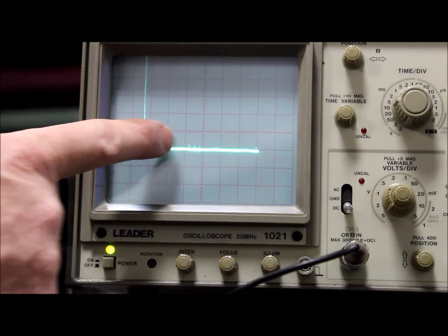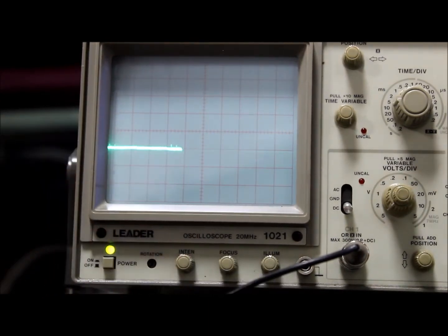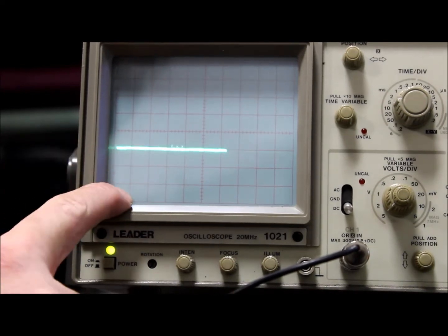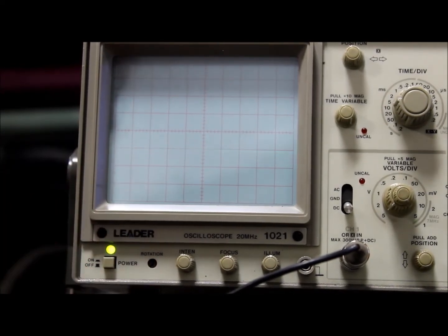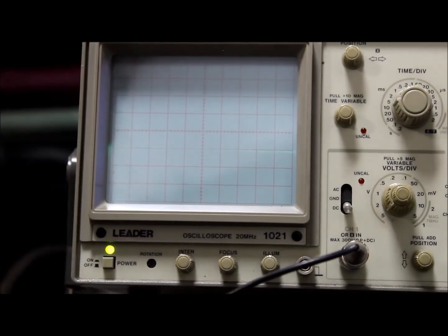So right here is where it's sitting at whatever battery voltage is with the car running. Looks like about 15 volts. And every time the computer pulls that circuit to ground in order to make the injector fire, you see the voltage sits down here at 0. And then when it ungrounds it, a big spike comes out of it.